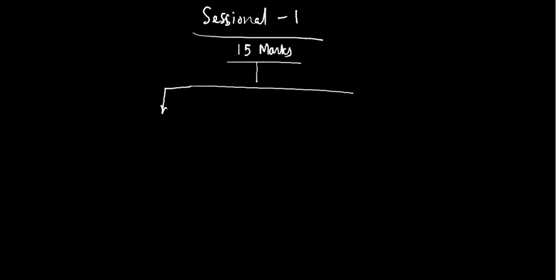We have seen the BCD arithmetic also. It's not the same as binary arithmetic. There's a difference. Just because the BCD numbers are defined only from 0 to 9, we have to make sure that the answer lies between those ranges, right? And we have also seen that calculators use those methods, BCD addition, widely used calculation methods.